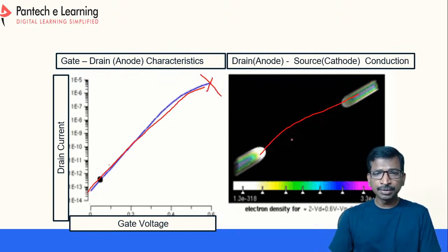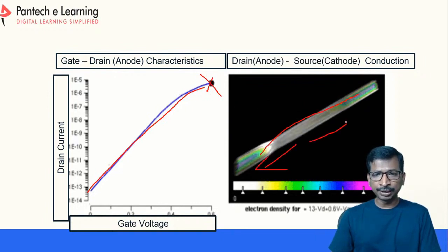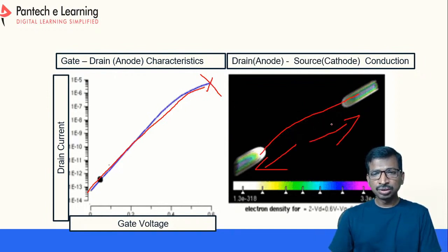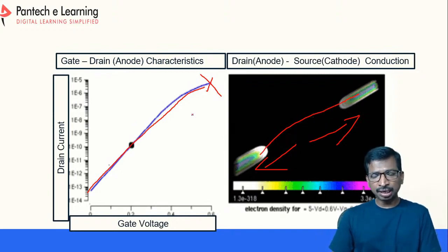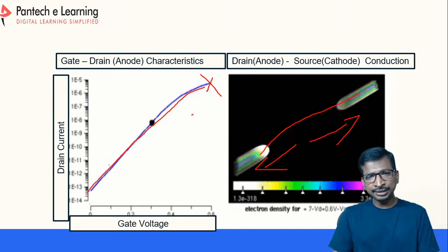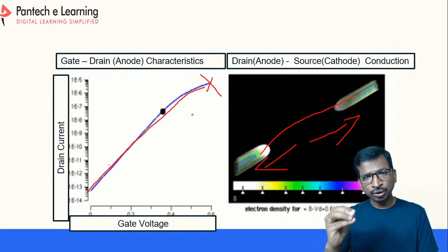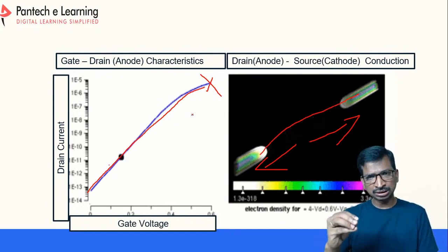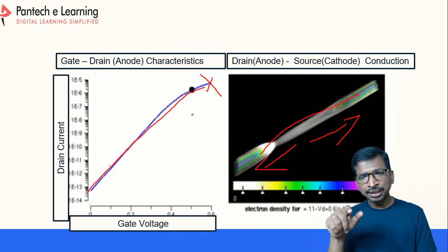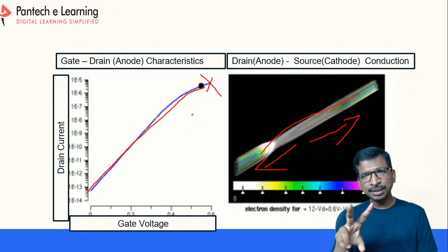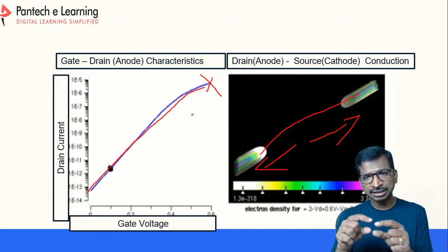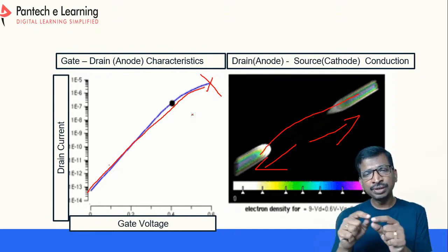If it is minimum, then the circuit will get opened, right? So this is a very simple animation video to understand the working principle of solid state switches. Whenever you apply a gate pulse, the two terminals will get connected. Whenever you remove the gate pulse, the connection established between the anode and cathode will get removed.